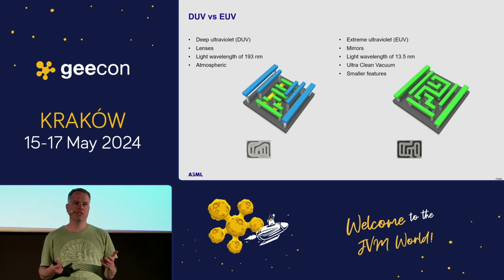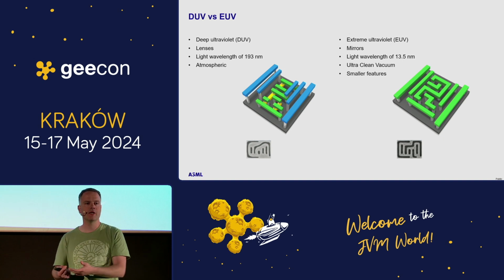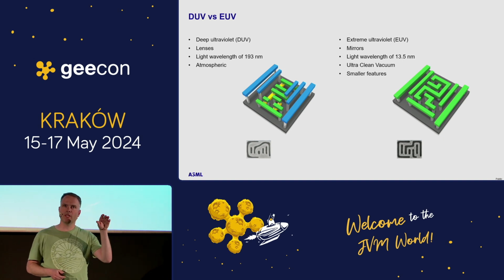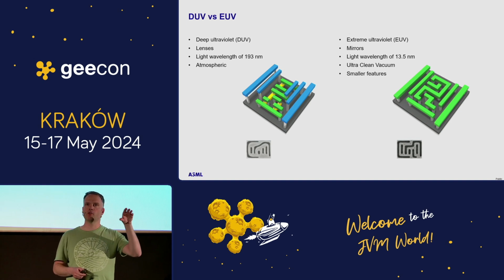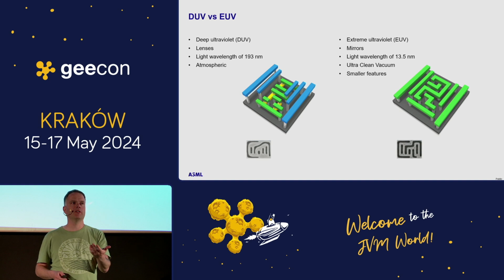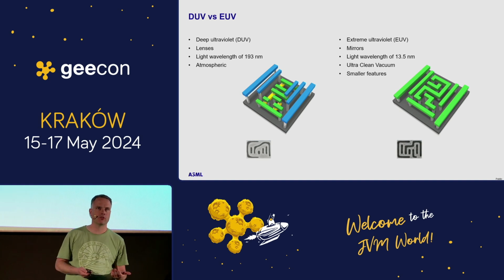So one of the benefits of EUV is that we can print smaller features, smaller transistors basically. But the other advantage is that for DUV, for some things, we need like 3 layers to achieve some functionality. With EUV, we can print that same functionality in 1 layer. So that's of course way faster, and you can achieve more complex structures that way.